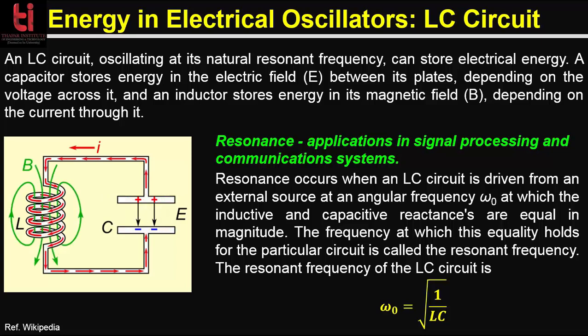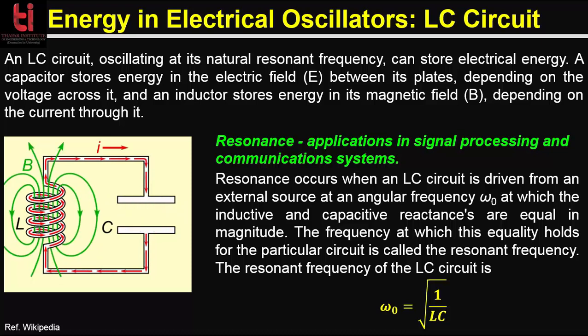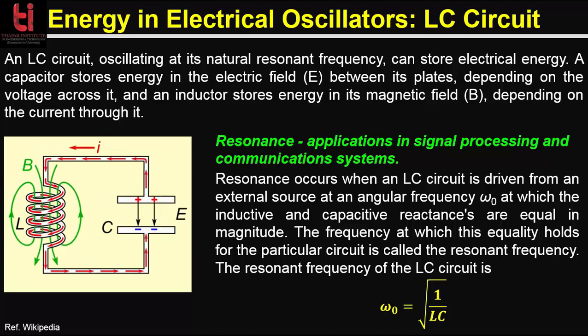The charge flows back and forth between the plates of the capacitor through the inductor. The energy oscillates back and forth between the capacitor and the inductor until internal resistance makes the oscillations die out. The tuned circuit's action, known mathematically as a harmonic oscillator, is similar to a mechanical harmonic oscillator. For instance, you can think about a pendulum swinging back and forth.